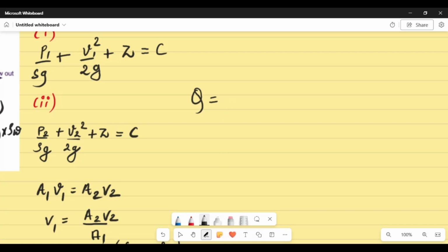How do you calculate flow rate? It is A2 times V2. And how is it so? Because you can write A2 times velocity, and velocity can be written as distance by time taken, and this value can be written as volume. Now if you ignore the density for now, because the density is the same for a flowing liquid, then this is the flow rate of the flowing liquid.